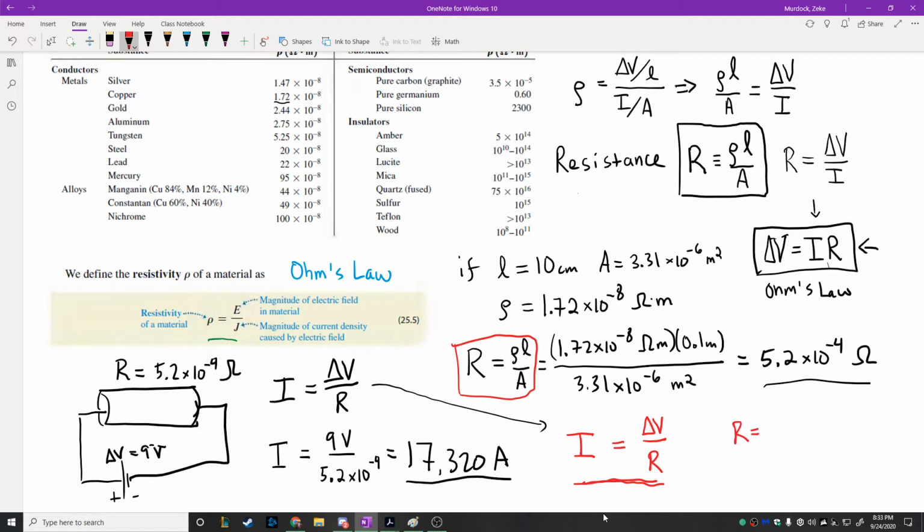Well, inside of a voltmeter, for example, like the ones that we use at school and some that you could buy at any electronics store, there is a resistance of about 10 times 10 to the 6th ohms. If I was to connect a 9-volt battery up to a voltmeter, the current that would pass through the voltmeter would be very, very small.